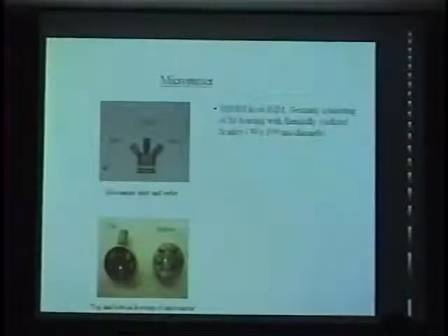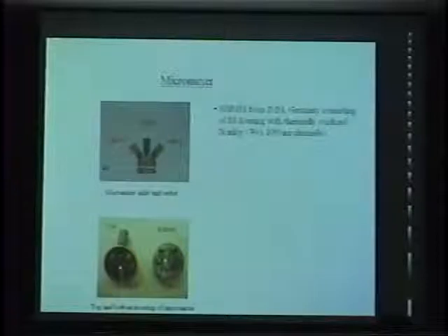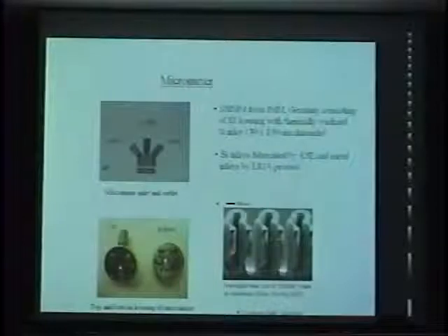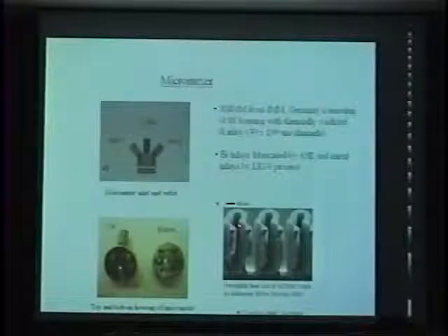The micro mixer we use is from IMM in Germany. Essentially, you have two reactants, two inlets go through, and here you can see some small chips, an interdigital micro mixer. Then the two reactants mix, and they go through the outlet, and the outlet goes through the temperature control bath. You can see in more detail the microstructure of the mixer. Essentially, one reactant goes through one set of interdigital channels, and the other goes through the other side.